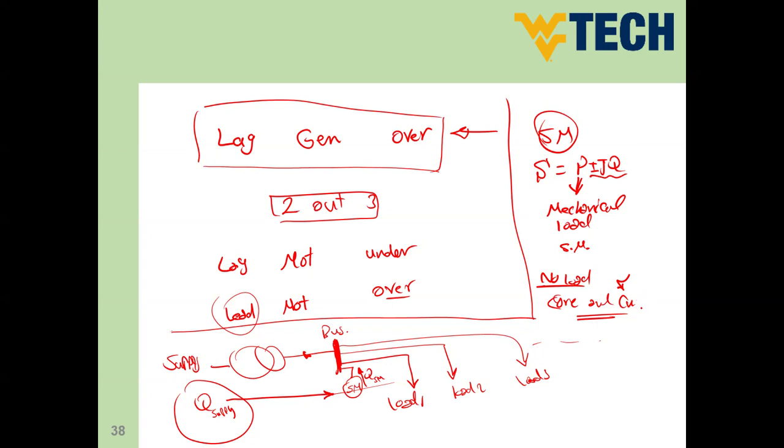This is because the rotor is moving with the same speed, which means we have zero copper loss on the rotor side, compared to the induction machine. So the copper loss on the rotor side is going to be just the field effect. So we don't have the same AC losses that we have in the induction motor on the cage or on the damper winding.